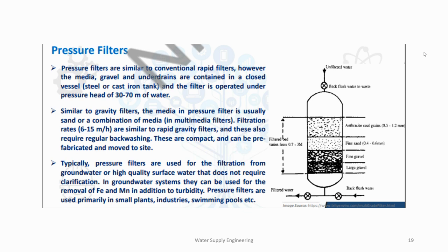So the filter bed can be either sand or multimedia. Rate of filtration usually varies from 6 to 15 meter per hour, and they need regular backwashing.